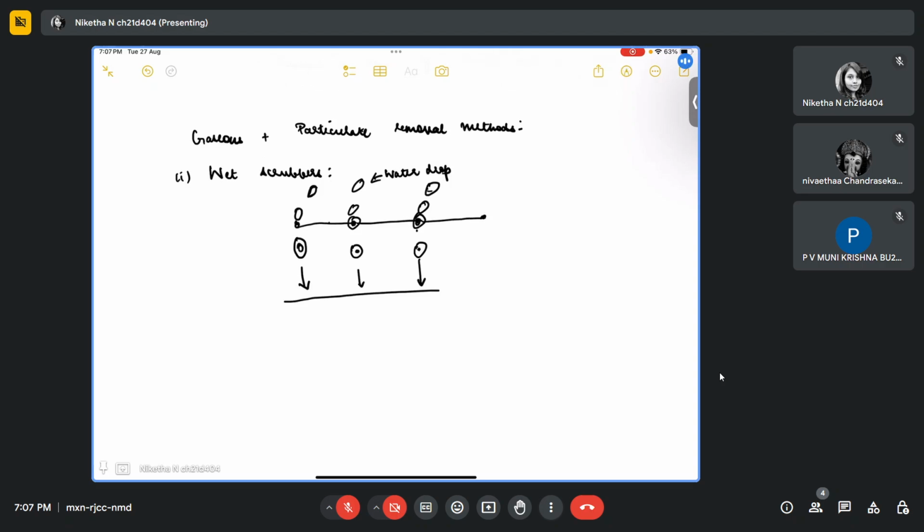So when you spray droplets of water on a stream of gas which contains particles, the water droplet will attract the particle and it will settle at the bottom. When you have more particles and proportionately more water, then the mixture of particulates with water will create a substance called a slurry.